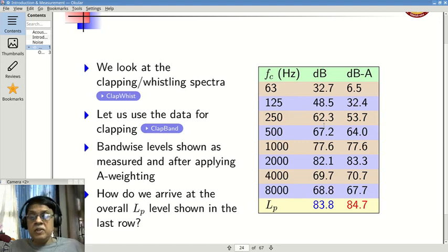With a 5 dB difference, we said 1 dB is the gap; 5 and 6 was 1. So if I add 48.5 and 68, obviously nothing is going to change. So if you look at the first 4 bands, effectively added up, it is 68. That is because 250 and 500 are 5 dB apart, so it will be 67 plus 1 dB, about 68.